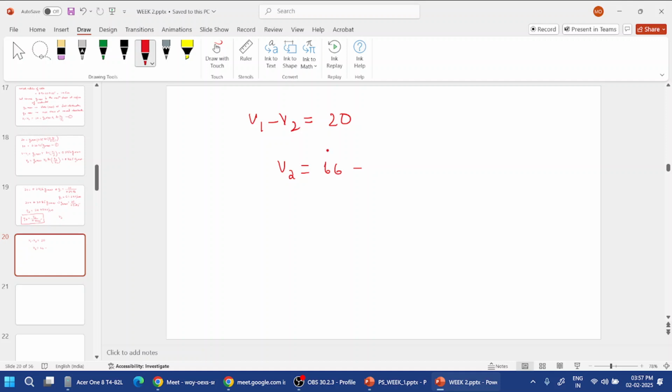Basically, V minus V1 gives G1 max, and V1 minus V2 gives the next. So V2 will be 66 minus 40, which is 26 kV, and from here we can calculate G3 max using 0.3165, which is 82 kV per centimeter.